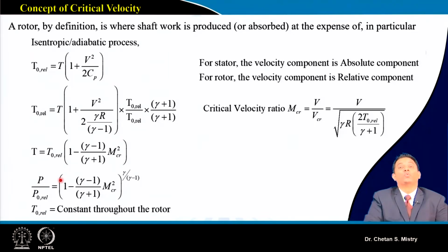Now when I say you need to do your rating problem, the question will come, how do we do it? I have this compressor with me, but what will I do with that? The question you need to ask is, do I know my flow parameters? Do I know my pressure? Do I have details about the temperature? Do I have details about the velocity? Based on the blades which are available, you can calculate my flow angles.